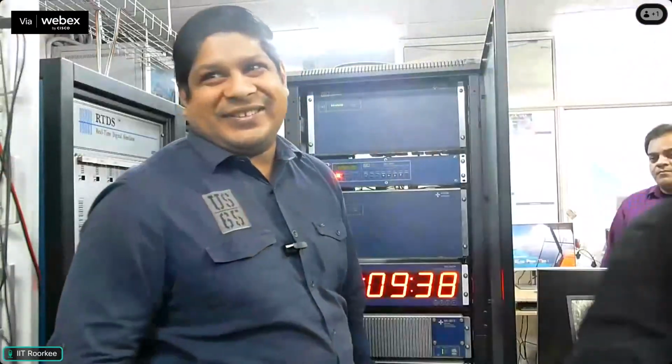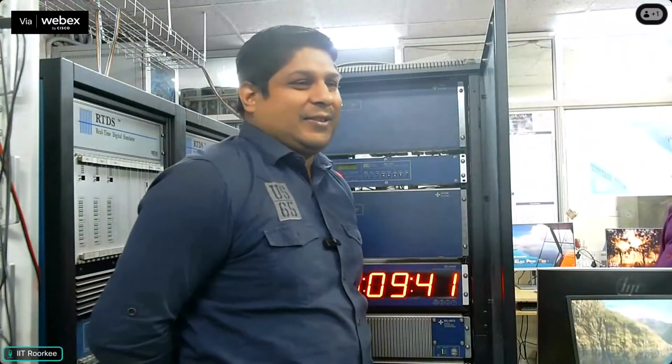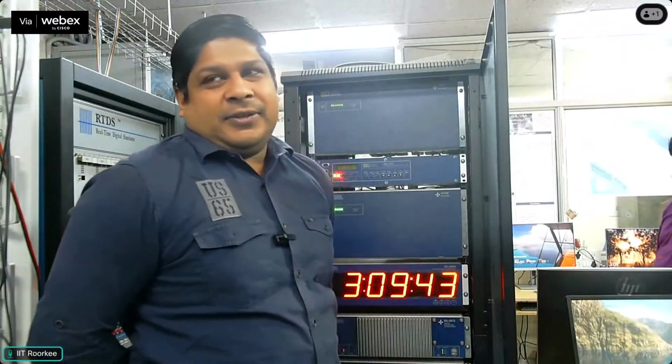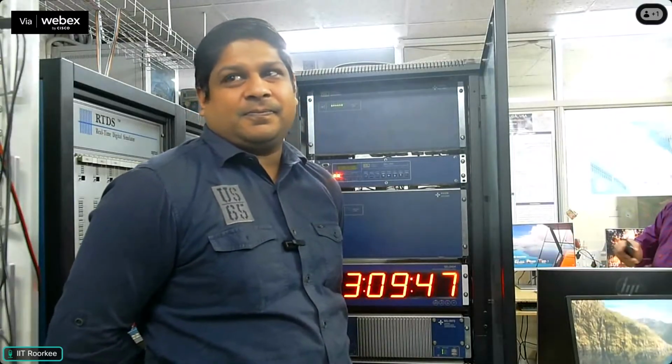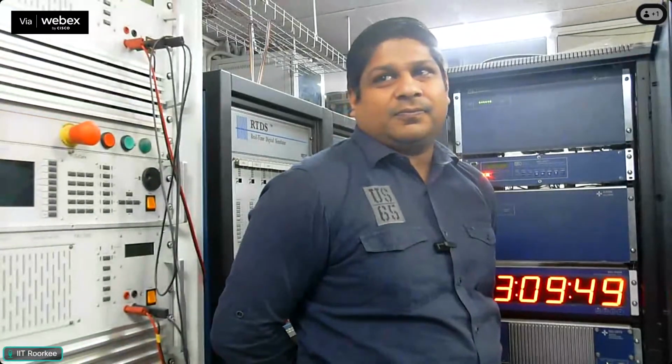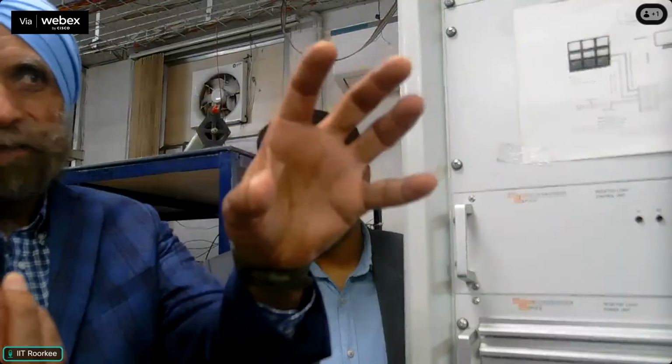The newer technology, if you have merging units, what we have done is basically out of the PMU, we have taken out the small part that takes the analog signal and converts it to a digital signal. And then the digitized values go to another unit, whereas a PMU has everything together.